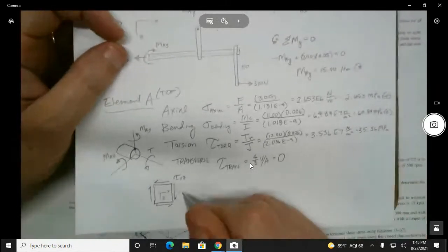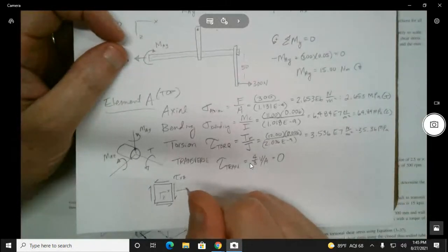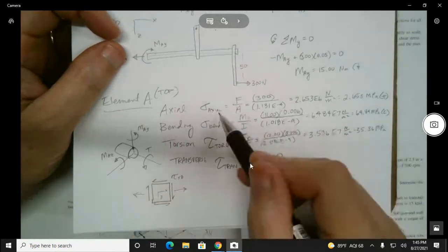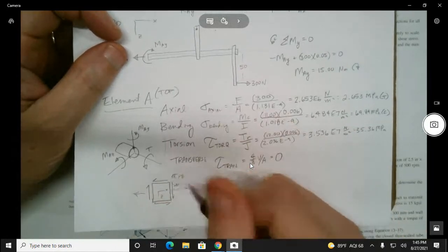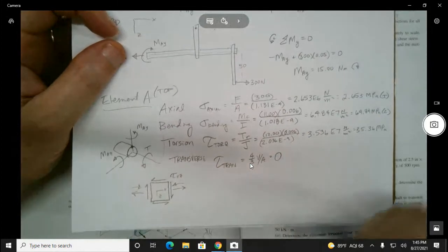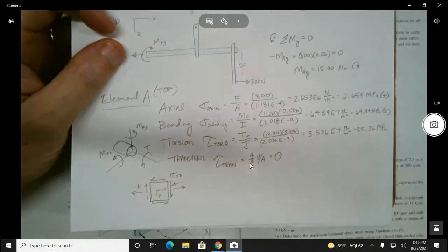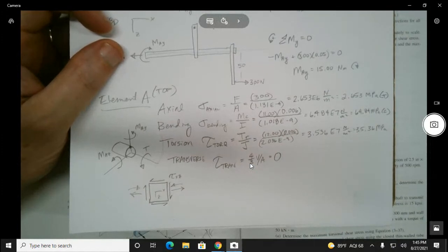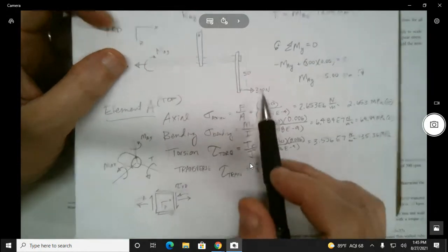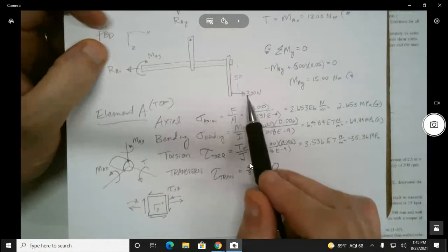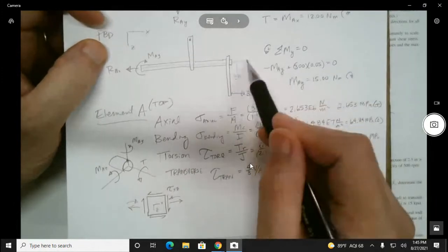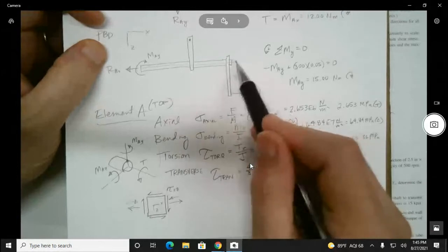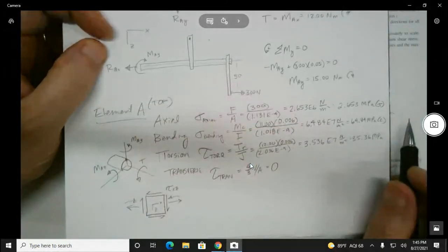Boring. Well, we do have the thing where we have tension due to axial, but we have compression due to bending. And it almost turns out, unless the thing was really, really squatty, that bending is quite often much larger than the axial. If I put a big force right here down the thing, then that doesn't cause any bending and would cause a lot of axial, right?